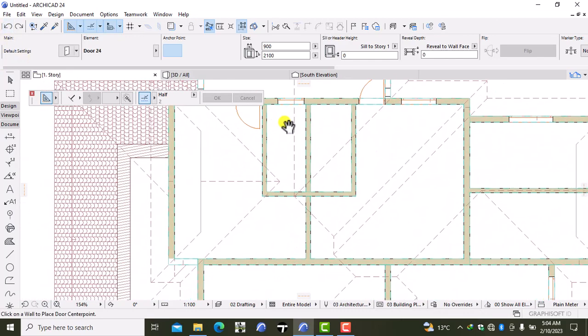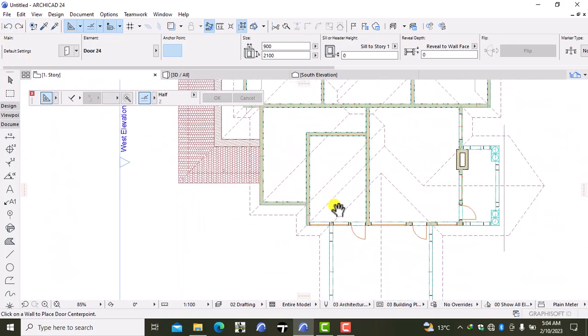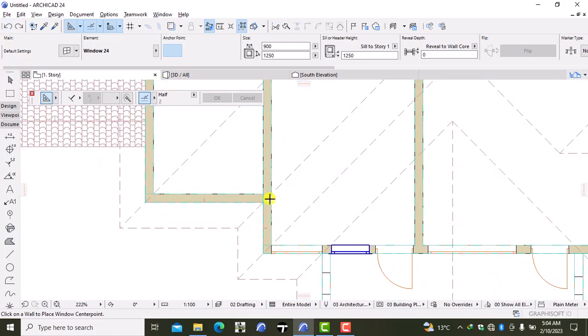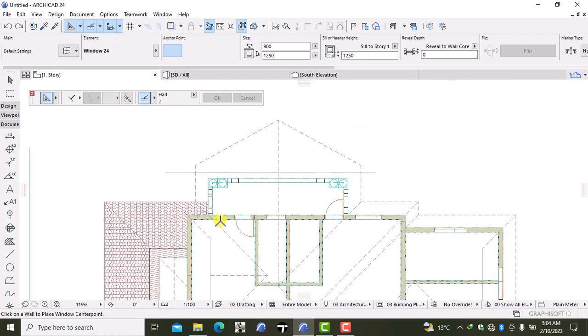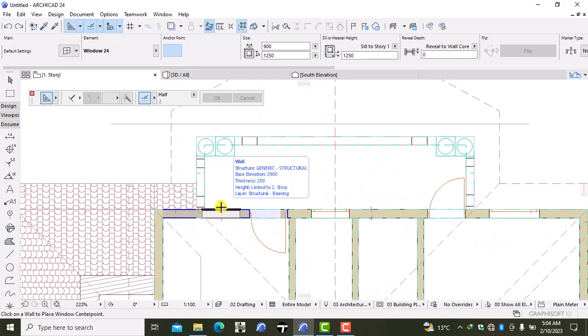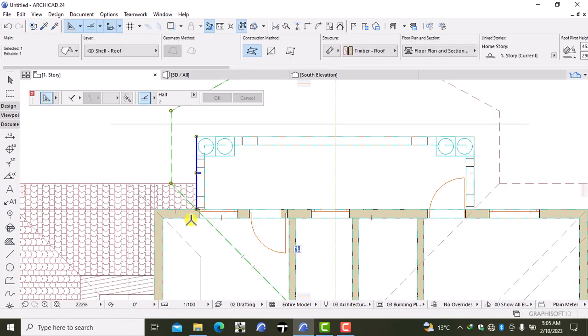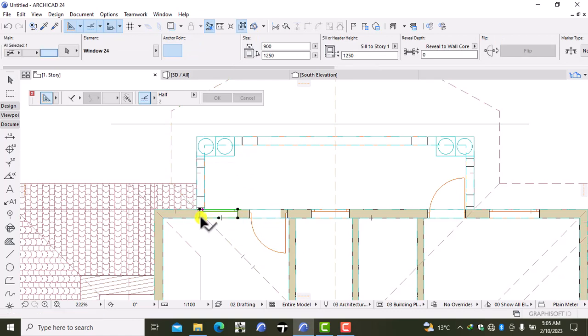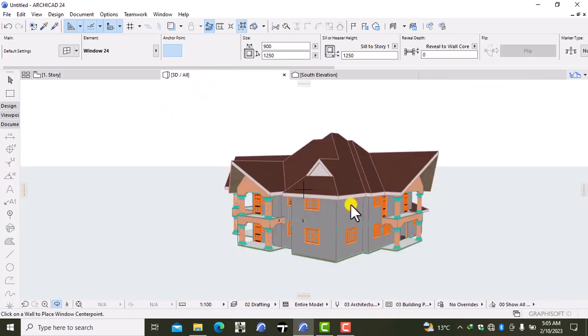I want now to do a window. Use that similar type of window right over here. You can just drag this from this edge, this edge, and drag it down. Control T. Can work with a height of 1500. And when we go to 3D, we'll have it as.